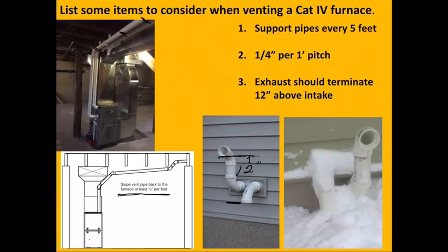You'd like to see 12 inches of separation between those. And in some cases, you actually are going to need more than that, and I would say that would be almost minimum. You're better off in most cases to have a little more separation, and this is especially true if you're dealing with multi-stage or variable stage equipment, where when you go into the lower flows, you're not going to have enough velocity to push under low firing rates.